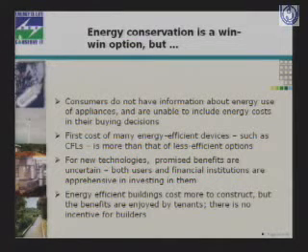There are enough technologies and construction practices that are known which can make very energy efficient buildings. Even in Delhi today, there are hotels made which use 400 kilowatt hours per square meter per year, and there are hotels made which use less than 200, maybe 160, 180 kilowatt hours per square meter per year.